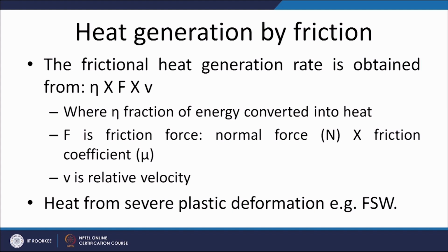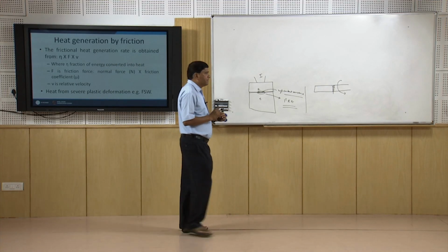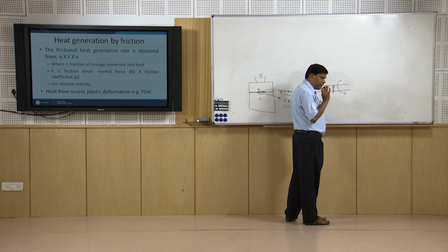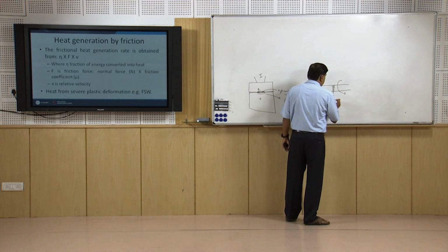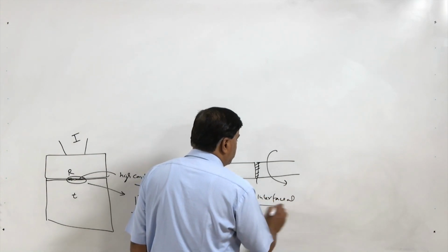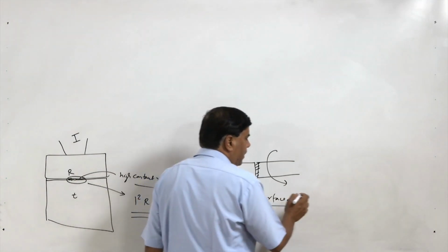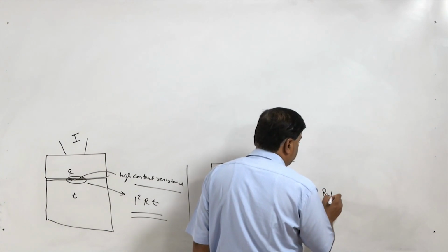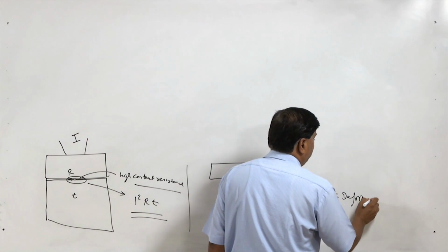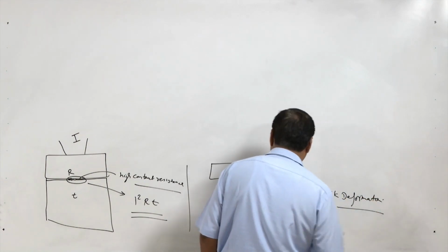The frictional heat is one thing, but in some of the friction based welding processes, deformation also takes place. There are 2 types of deformation. One is interfacial, which is typical in friction welding, and another is bulk deformation, which takes place in the case of friction stir welding.